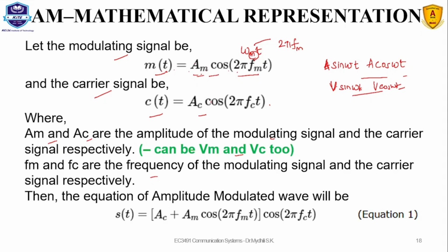So when we are solving this equation, we will get, by using trigonometric solution finally, and based on the definitions, this amplitude modulated wave can be simply represented as the output v of t equal to Vc plus Vm cos omega mt, into cos omega ct.